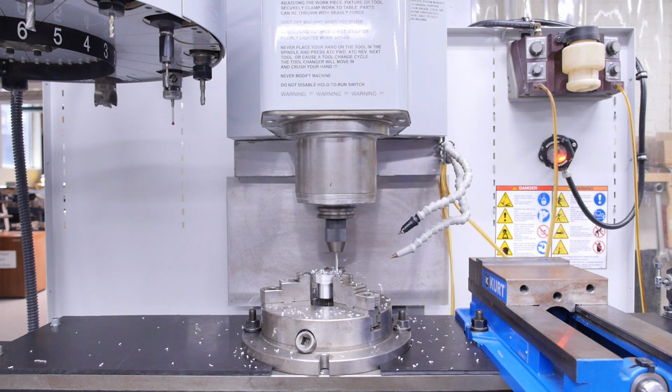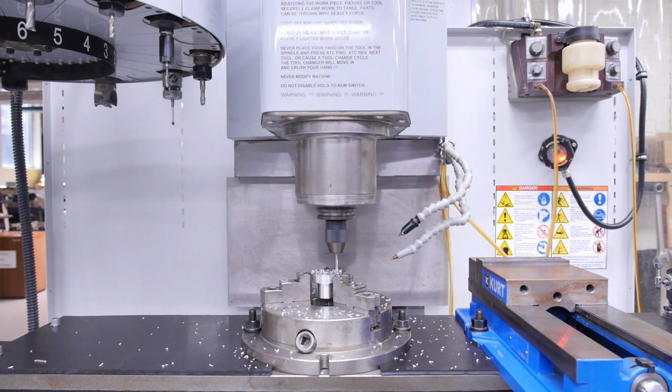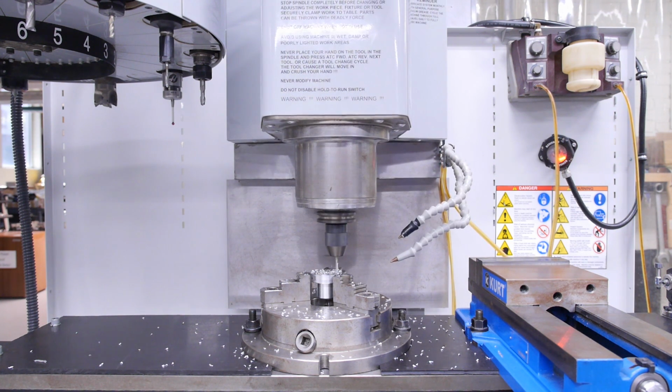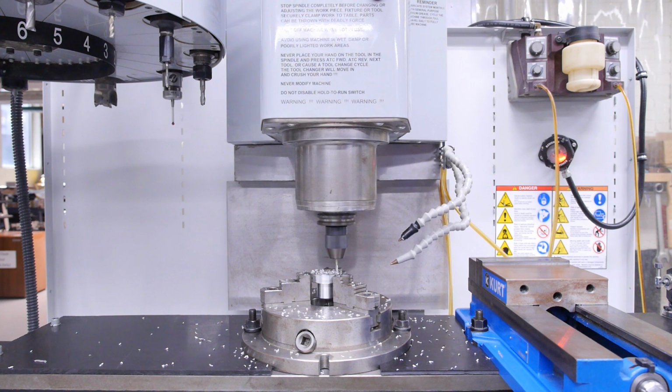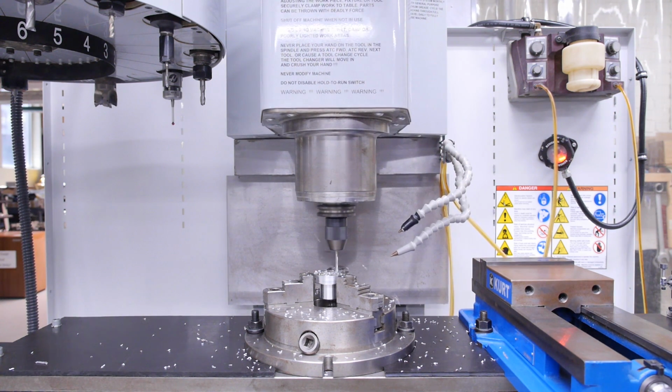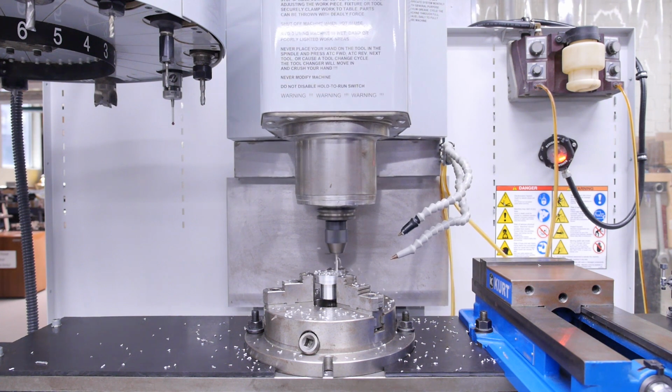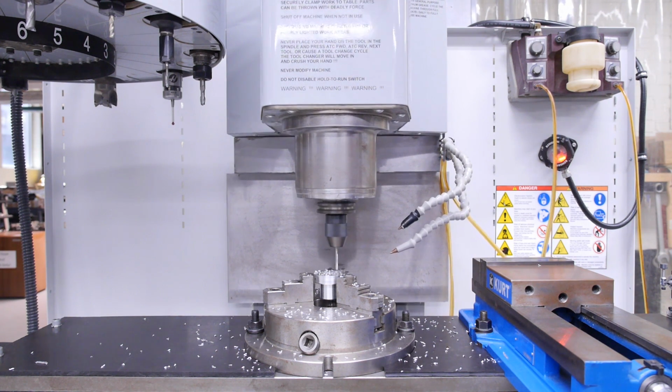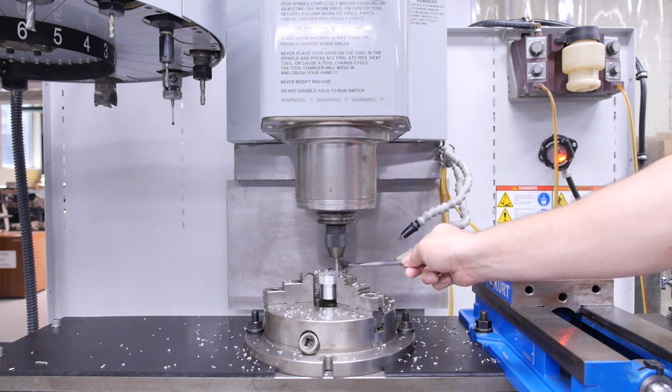As you can see in the video, I prefer to apply the oil to the part manually versus using the air oil mister on the machine because the mister is more difficult to talk over. However, when applying the oil manually, after the machine drills or taps 3 or 4 holes, reapply a little bit of oil to the drill or tap.